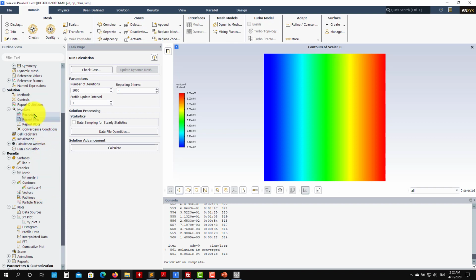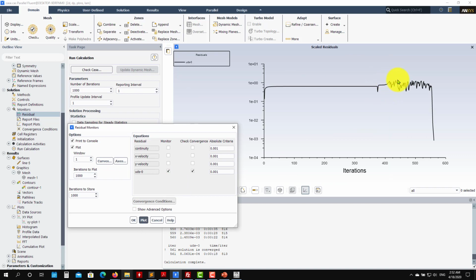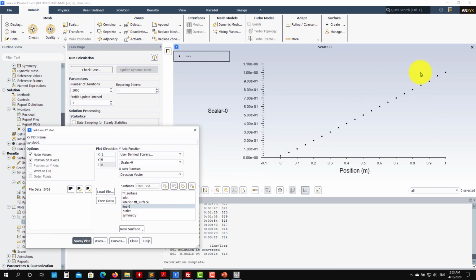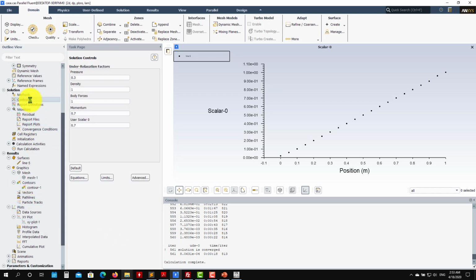Okay, you saw here the effect of a bad initial condition. See all these oscillations, and you can see that everything can be controlled. So if you choose a lower under-relaxation here, you will smooth these oscillations, but it will take much longer to converge. And you have your solution. So feel free to play with this case. You play with this under-relaxation.